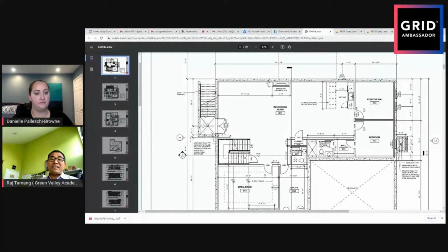Because if it is 1 inch or a half inch or even 2 inches wider, I can always fill it in with a stud or plywood, or even fill it with foam, right? Yeah, you can shim it up. Yeah, you can do it easily. But if the concrete wall opening is smaller than the actual door, now you are in trouble.